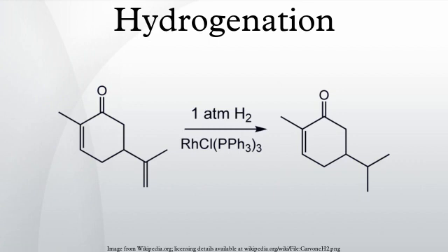Industrial reactors. Catalytic hydrogenation is done in a tubular plug flow reactor packed with a supported catalyst. The pressures and temperatures are typically high, although this depends on the catalyst. Catalyst loading is typically much lower than in laboratory batch hydrogenation, and various promoters are added to the metal, or mixed metals are used, to improve activity, selectivity and catalyst stability. The use of nickel is common despite its low activity, due to its low cost compared to precious metals. Gas-liquid induction reactors are also used for carrying out catalytic hydrogenation.